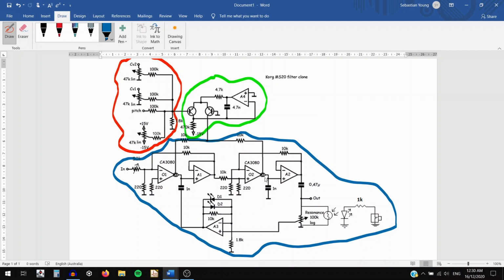But moving back to our filter circuit, which I'm not going to go into the absolute details about, because I'll be honest, I don't totally understand it myself. But the CV input basically controls how much current is on the output of the OTAs, and therefore where the cutoff frequency lies. Again, details on how OTA filters work can be found in the data sheet, which gives an absolute wealth of information, more than I could surmise in a few short sentences.